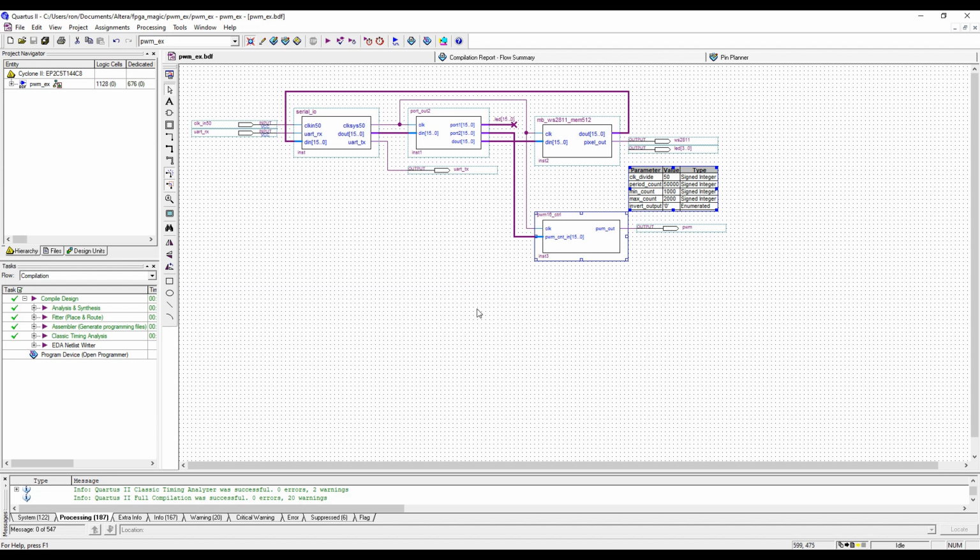The macro shown in this design has a 16-bit input which controls the pulse width modulation output, which starts at 0 and ends at whatever count you input. Also in this design we have included a 16-bit output port to drive some LEDs on our daughter board and a macro for the WS2811 to add a little light to the show.